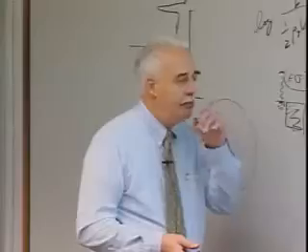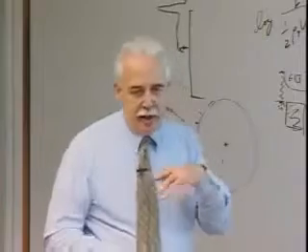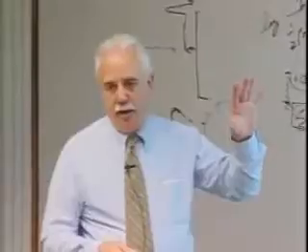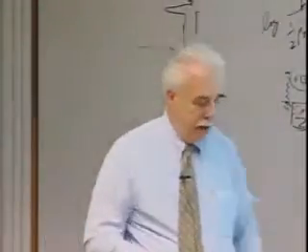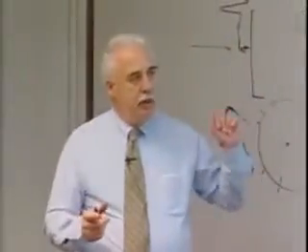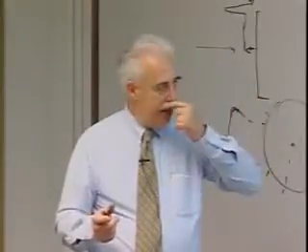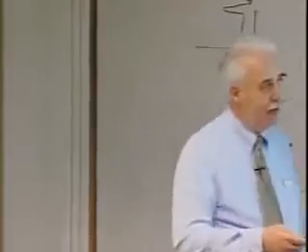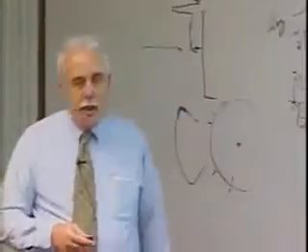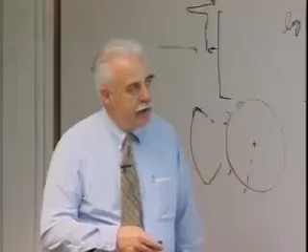Okay? Now, I mentioned 3 levels of aerothermodynamics. The design level, well, I'll get into the design level a little bit later. The first level was basically the Apollo technology. We went to the wind tunnel, we correlated the distribution of heating on the shuttle relative to a reference, and we used a 1-foot sphere as a reference. And I gave that to the flight mechanics people and said, do not violate these constraints. So they developed the flight mechanics control and everything else to fly right along here.